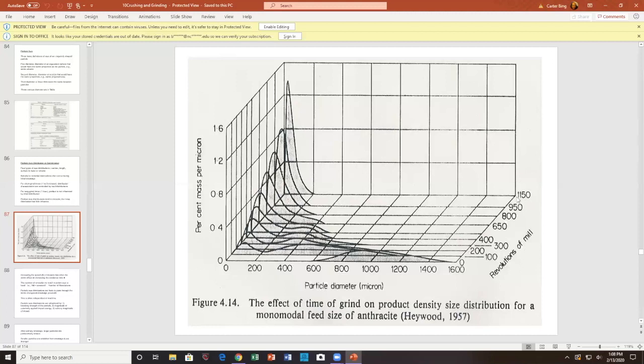So the process is actually done. Now, from 1100 revolutions all the way up to 2000 revolutions, this material has agglomerated. And now this distribution no longer exists, but there's agglomeration that's occurred that moved the size of the particles to a larger size. You may still have the log normal sitting there with the powder, but there may be a distribution of agglomerated material.